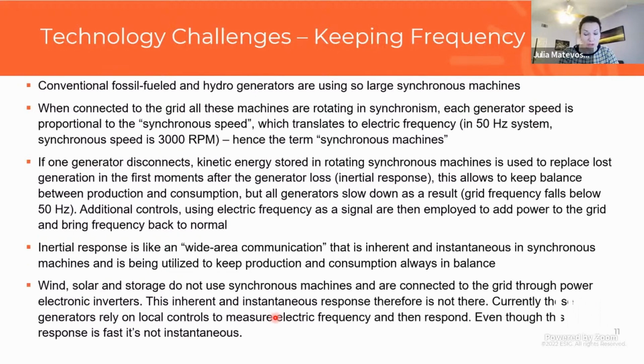And then there is a new technology, a new way of inverter controls. Janusz, I think somebody already mentioned grid forming controls, which allow inverter-based resources to act a little bit more like synchronous generators and provide services nearly instantaneously and inherently, and with that support system reliability. With proliferation of these grid forming inverter-based resources, you can theoretically go to 100% wind, solar, storage on the grid instantaneously. Some of the islands, as you've seen on my first slide, are already going to 100% penetration, and that is possible because they have some grid forming inverters on the grid.